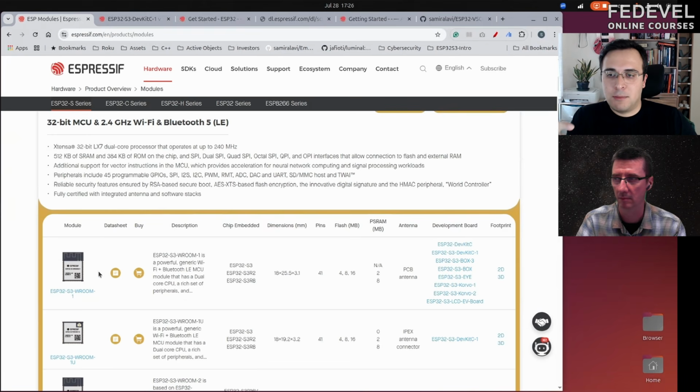And the good thing about the modules is that they have already passed these certifications. And if you are designing a product and this component or this module is the only part that is doing the communication part, you don't need to do the retesting for the final product.